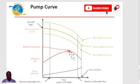The BEP, as you see in some texts, is usually specified on the pump curve itself. If the best efficiency point is not specified, you have to contact the pump manufacturer to furnish the best efficiency point on the pump curve.